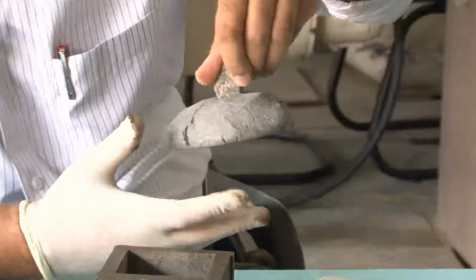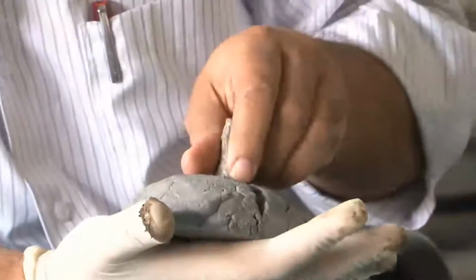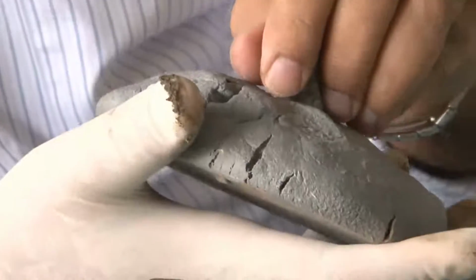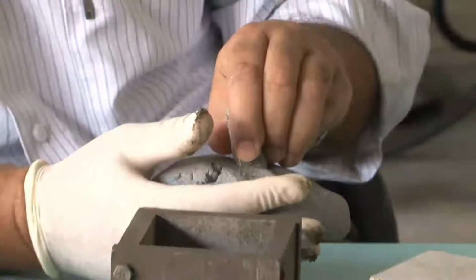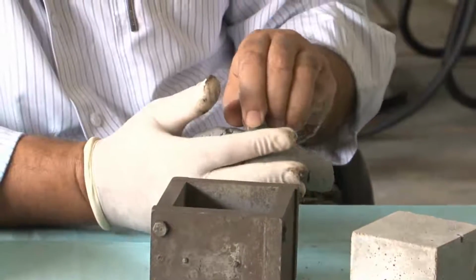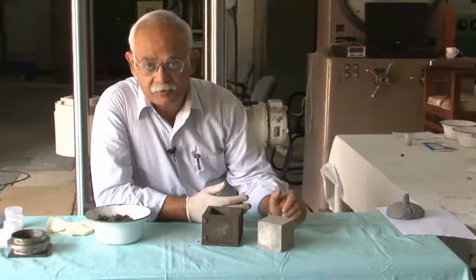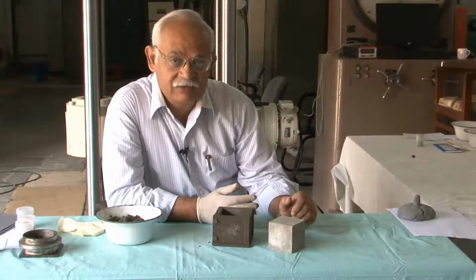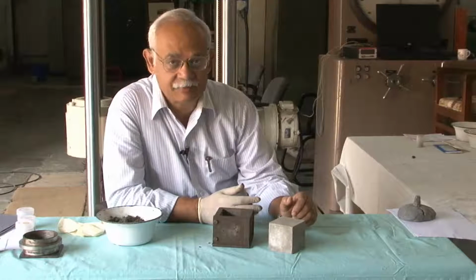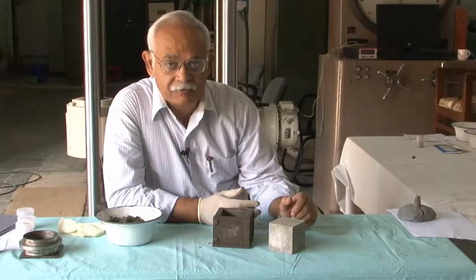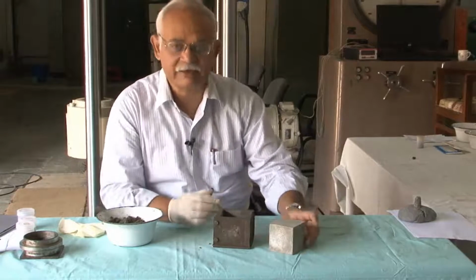These are shrinkage cracks because of the heat of hydration and because of the dimensional changes in the cement as it hydrates. Because of this problem with cement paste, we do not use cement paste and rather use mortar. However, we have to be careful that the properties of sand do not affect the strength of the cement which has been determined, and therefore, what we do is use standard sand.